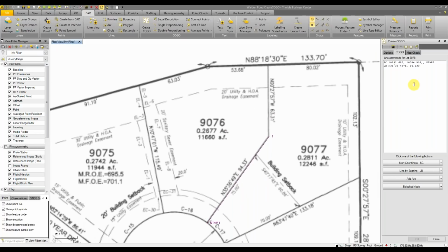So far, the plan is matching pretty well. I've already built this out and georeferenced the plan. If you put a plan in, it's a very small chance that it'll line up on your first try. You'll have a paper plan in front of you on your desk, which is what I would prefer to be doing too. So now I want to do another line by bearing.